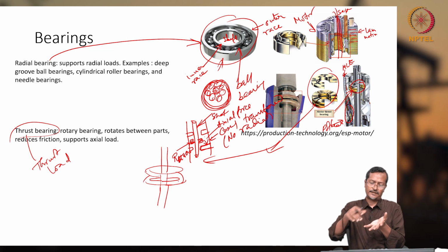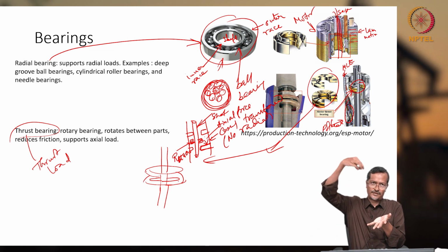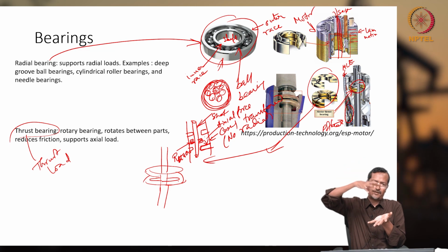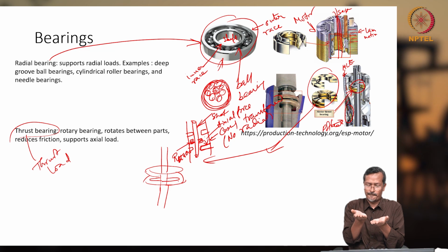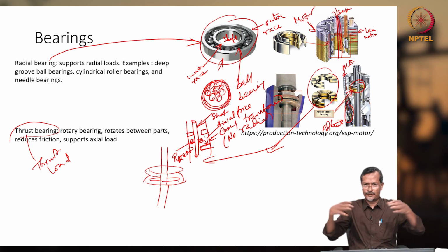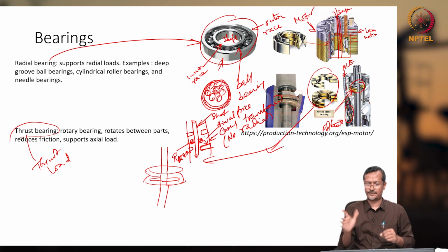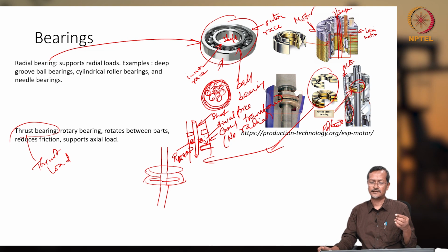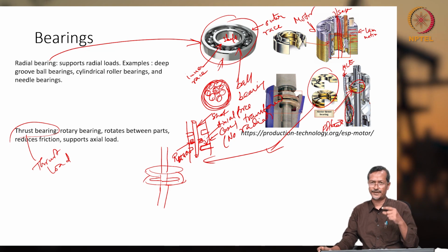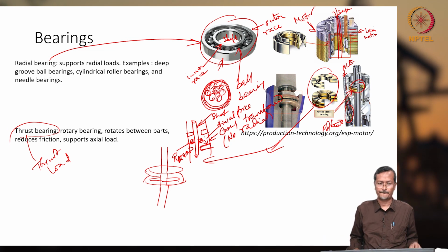Thrust bearing: two plates are there, in between the runner and shaft rotating, the axial force is transferred to this bottom plate or top plate, and the bottom plate and top plate are connected to your fixed casing, with the shaft and runner rotating together. So this way, this radial and thrust bearing will be there in your pump also, in your motor also, in your protector section also.